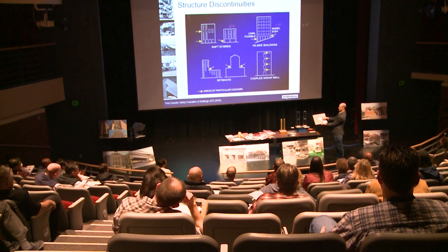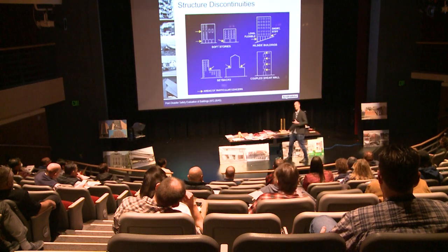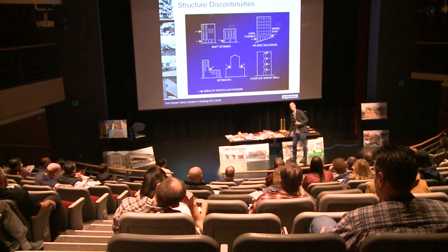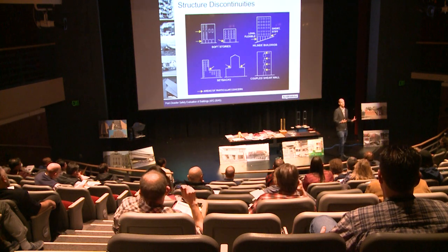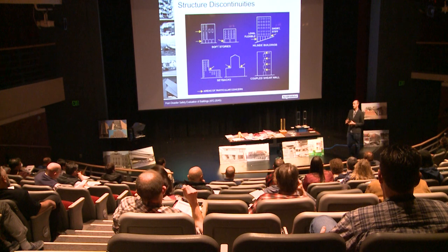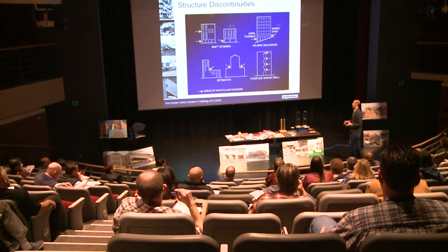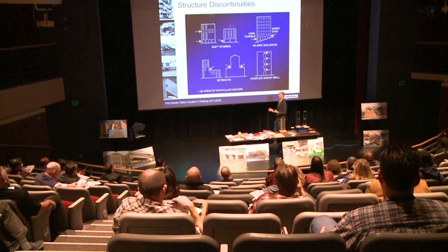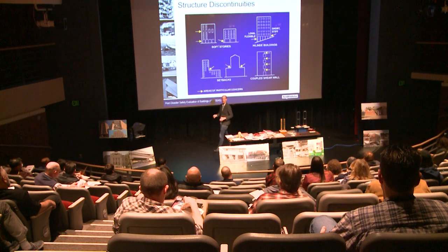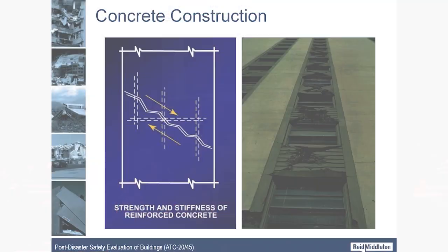And because of that, there's this global torsional behavior. But the main takeaway as we think through these examples and as we look at damaged buildings is to recognize that stiffness inherently attracts more load. And so as we think through looking for where the damage might be in a building, look for the stiffer areas first, because they're more likely to take more than their fair share. That makes sense?